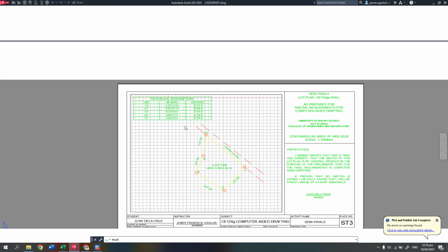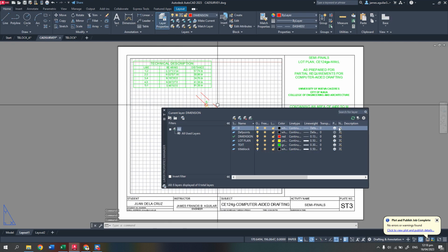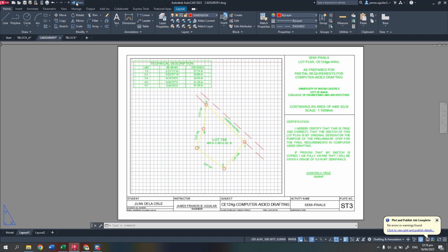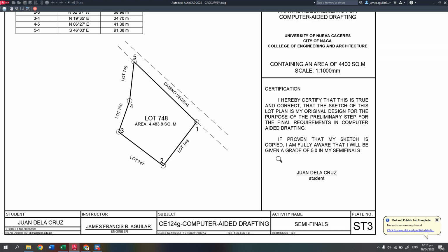But take note, before you hit print, if you encounter invisible line, just check your printer. So you must not have a cross out icon for the printable layers. So next is, once you have the print options, preview it, then check. This is the actual PDF copy.